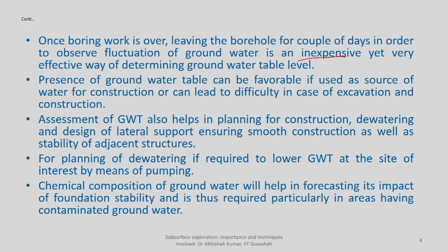So, that is the assessment. Once you are assessing this groundwater table well in advance, you can actually be very clear with the planning. You can be very clear whether dewatering is required. You can be very clear whether lateral support is required, and you can go for design of what kind of lateral support is required.